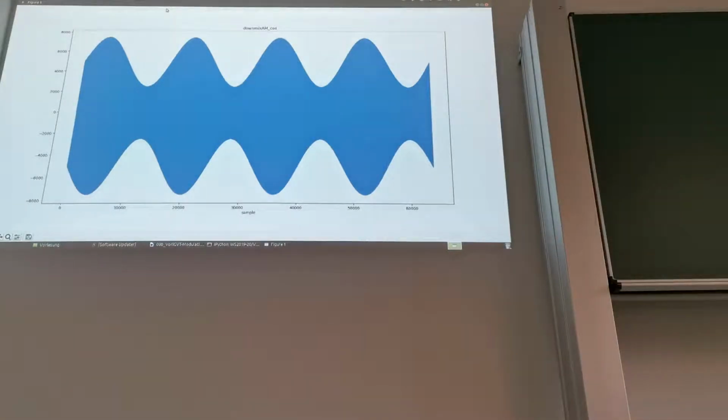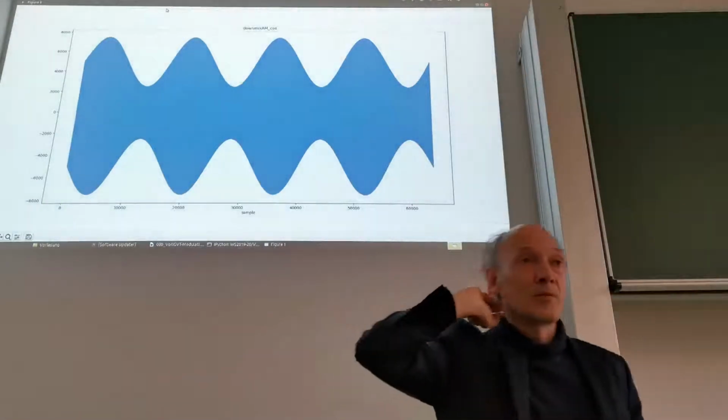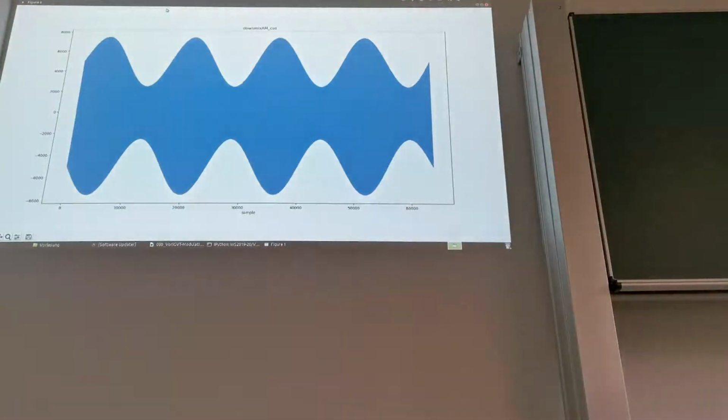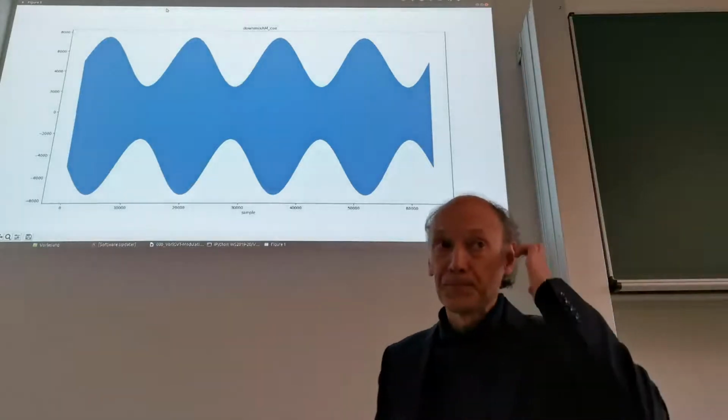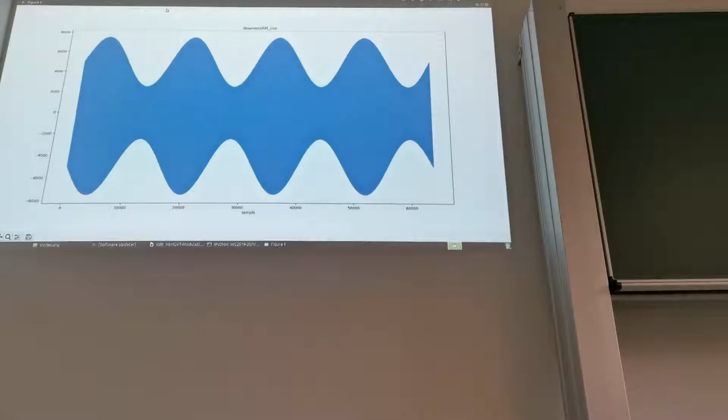So in this case, actually, we don't even need this cosine part. But imagine we have a phase shift on the transition between the transmitter and the receiver. Then we don't know if it's a sine or cosine or in between. Right? And that's why we need to have these two carriers. Basically, both together give us a robust decoding or demodulation.